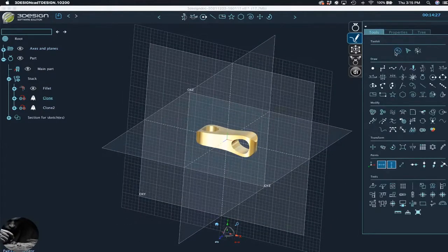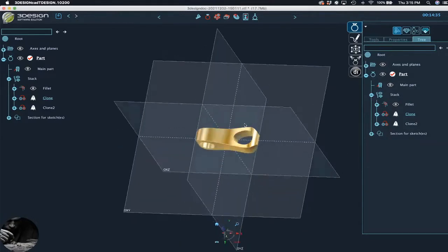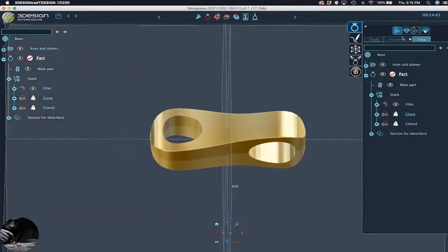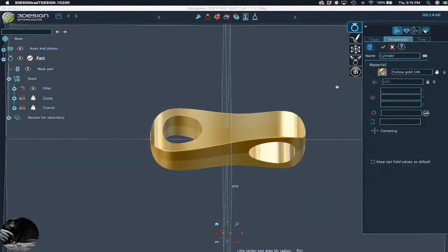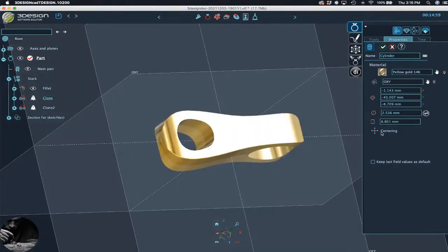But what we do need is to create this sprue that'll hold these links in place. So depending on your understanding of casting, you can actually just come in and we can build our sprue directly out of this area here. A simple way to do that would just be to take this cylinder, create one cylinder, pay attention to your widths, and make it a nice length and connect it there. Just center it back up. Okay, so here we have that.